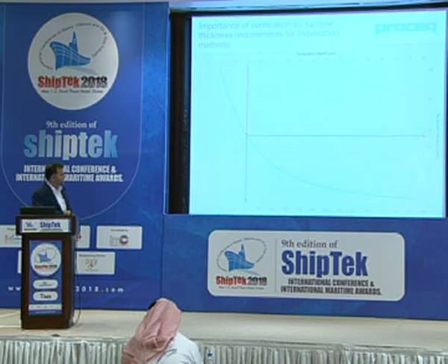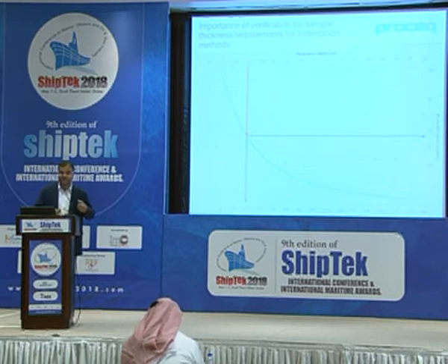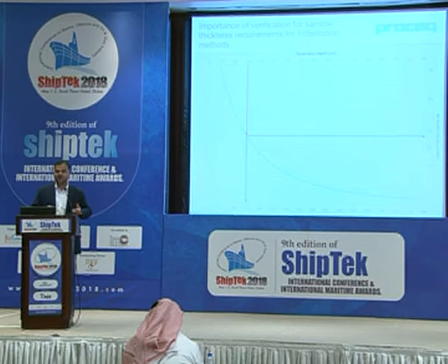It definitely depends on the hardness. It's almost 47 HRC. At this hardness, the indentation depth would be about 15 microns, and the test piece thickness required is about 150 microns. So very thin. We'll be able to measure a 0.15 millimeter thickness sample using this method. It's very accurate, being a static method and the most established in the market.